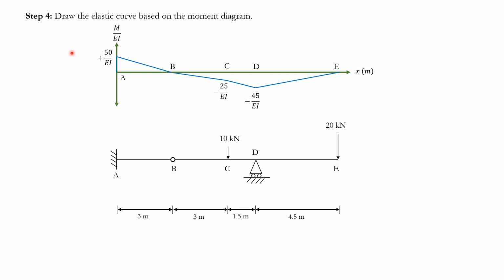As I mentioned before, the moment diagram here is going to be very crucial in drawing the elastic curve. Of course, as you solve more and more questions about the elastic curve and how it looks, after a while you just get a hang of it, right? You just see, okay, maybe I know what it looks like, this force is larger, and so forth. But if you say, I don't want to complicate stuff for myself, I just want to be safe, I would say the moment diagram is the best approach to start that part.